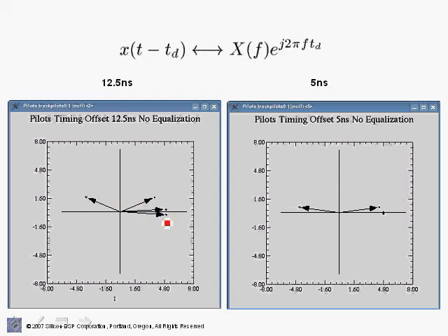So if we take a good look at this, since we know what the frequency of the pilot was and the amount of phase shift, we can actually estimate the time delay on a per pilot basis and then average over the 4 pilots to get the time shift, and then correct the time shift for all the data carriers. Now that's one way to do it. Again, we're not getting into the implementation, just showing you the concept.